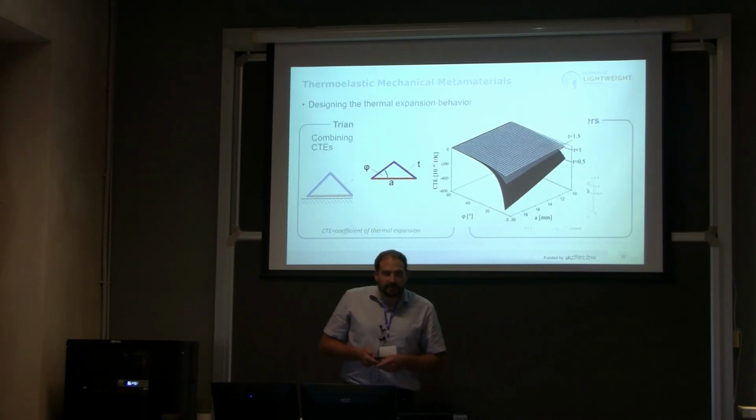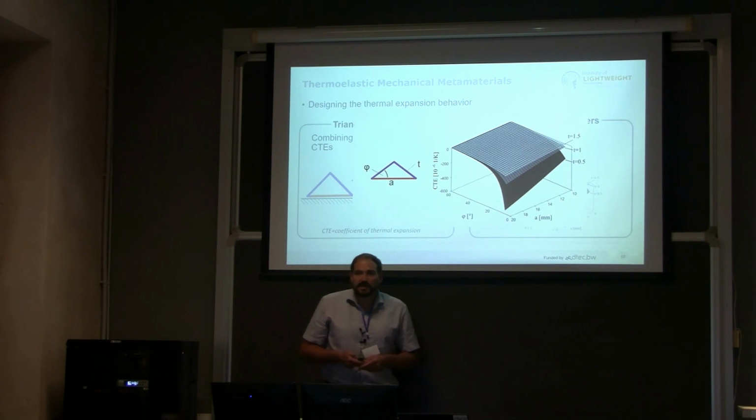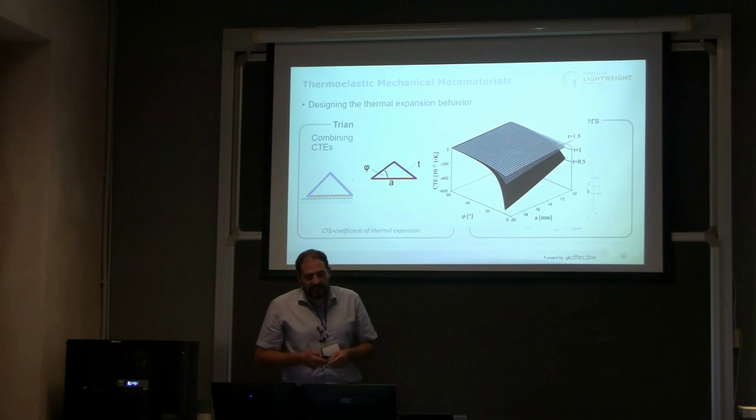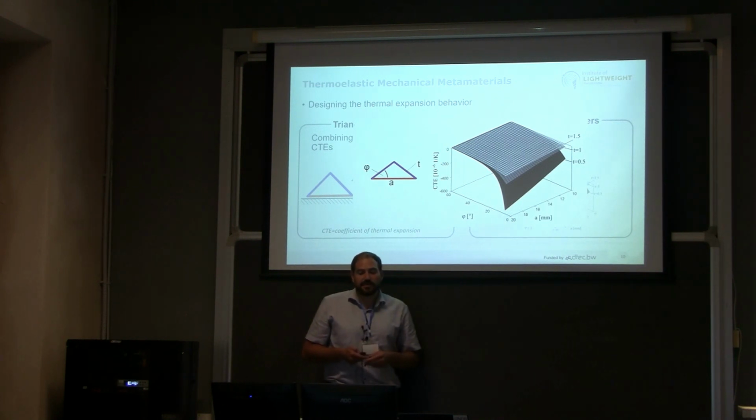And we made some first investigations. Here you see the CTE over the angle phi and the edge length A. So you see, if you go for very low angles and very high edge length, you can reach very high negative thermal expansion.